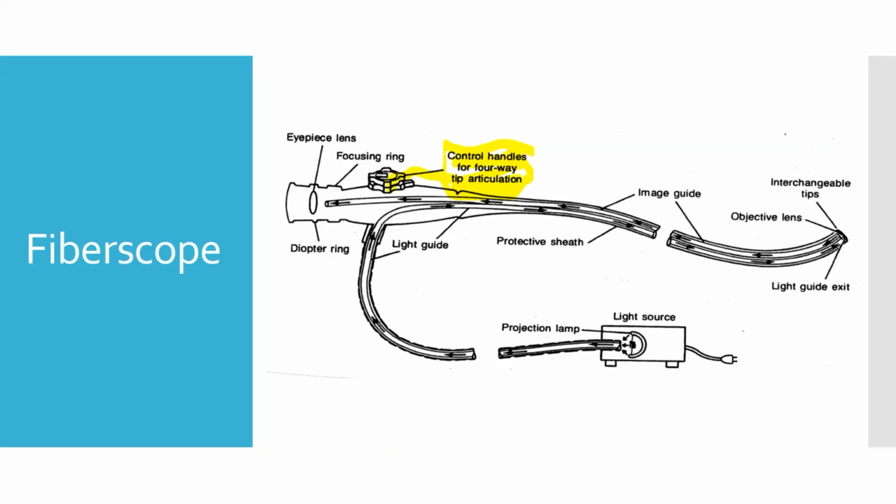If you're using an articulated scope, please be careful. Don't force it. You only want to bend it or move it using the control. Don't grab the tip of the scope and try to move it around. That can damage those very fine wires that are used to actually control it. In fact, with our video scope, the controller operates little motors that move the little wires and everything. So they're very precise and they're very easily damaged.